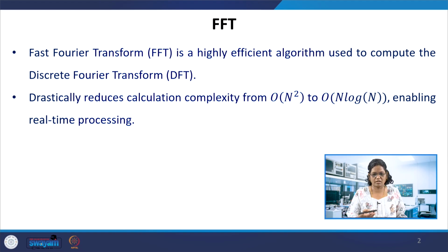and divide them into even and odd samples. That means separating them as even and odd, and then from the even samples we again separate even and odd, and then even and odd, and so on. If we do this, the n-point DFT can be reduced. It depends on the stages and on the length. If n is equal to 8 samples, then we'll have 3 stages of computation.